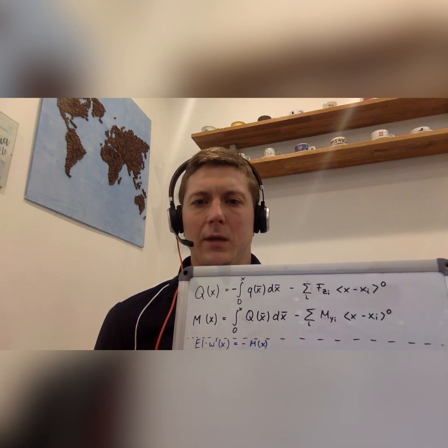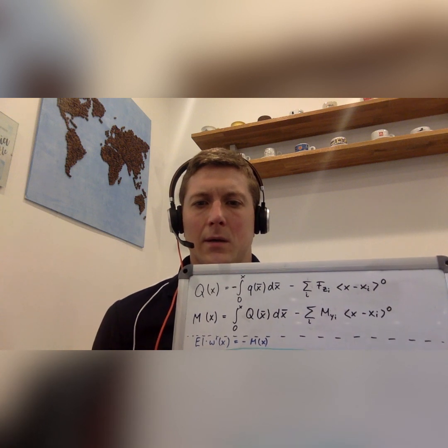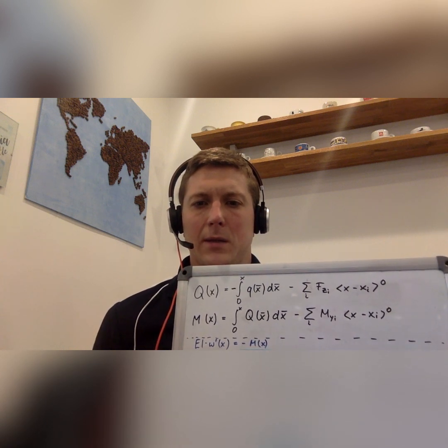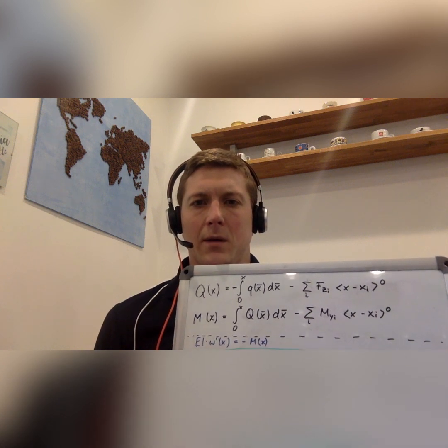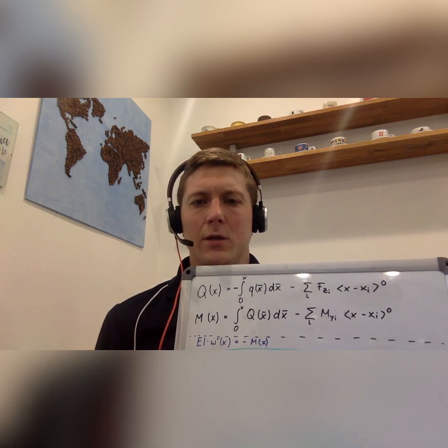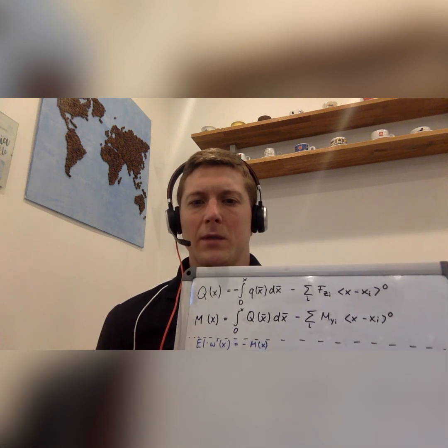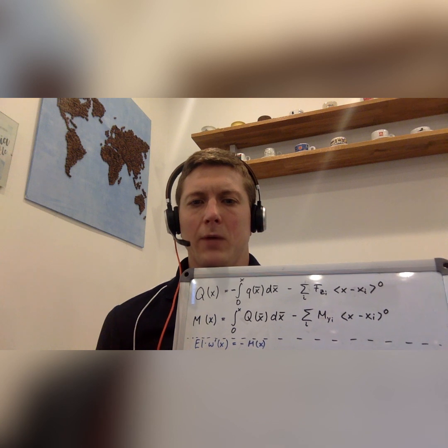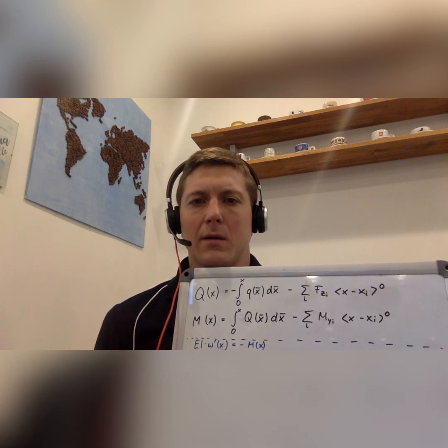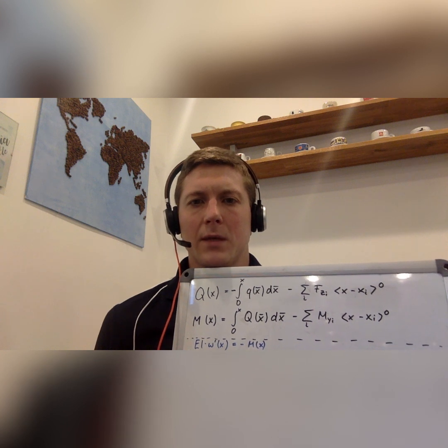This equation can be calculated out of some model assumptions where you have a linear ansatz in this case. What you have to keep in mind is that there is this M, the bending moment, and this leads to the deflection or the inclination of your beam, and in front of this w prime, which is the derivative of w, there is this E times I. E is something we already know out of the tensile bars.